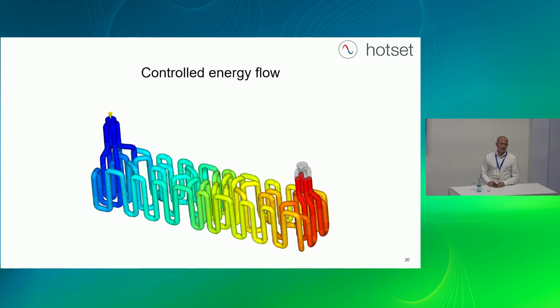And he said, "I'm using just one machine. I'm using the water from my cooling plant, as the other machines are running with normal modes, nothing special. And I'm running a 3D printed insert in this machine. During injection, the melt was shocked by temperature, and the melt gets stuck. It can't fill the part completely."